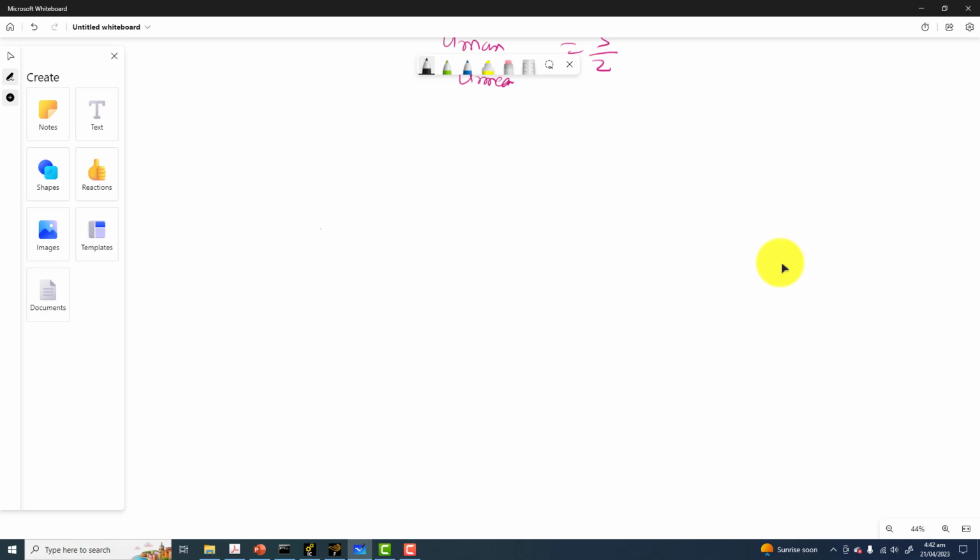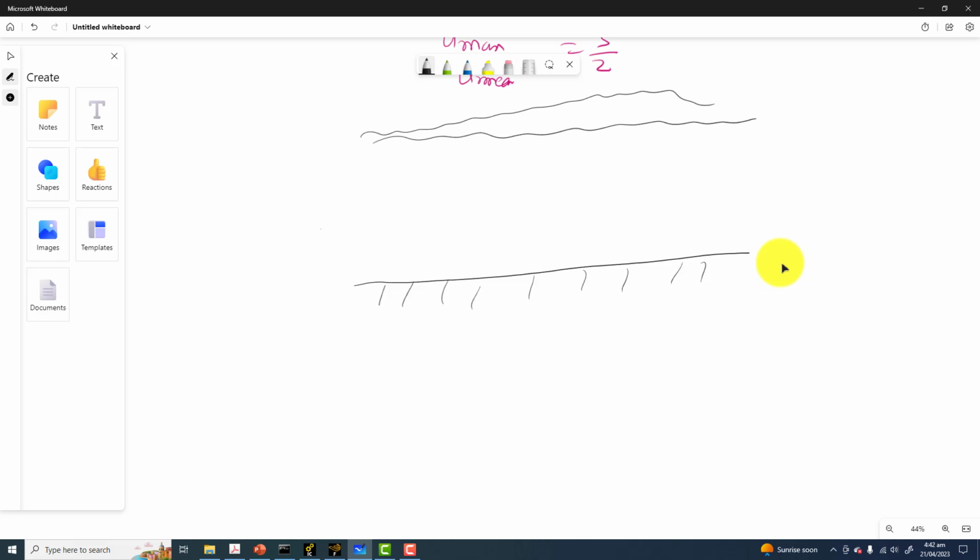So the difference here is that we have one plate on the bottom, and on the top, instead of some fixed surface or rigid wall, we have a free surface. So the velocity profile is like a half of the parabolic profile, and it is something like a flow over a flat plate, but it's not exactly the same.